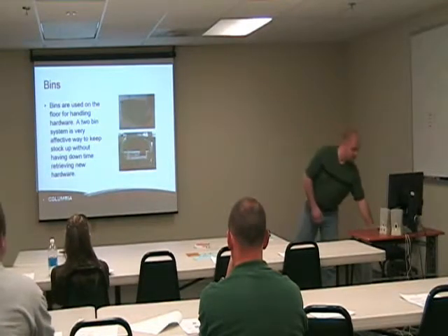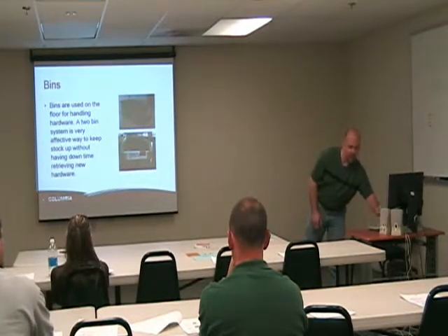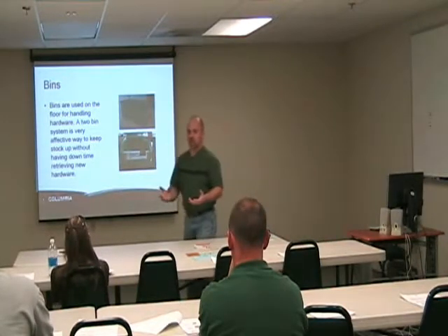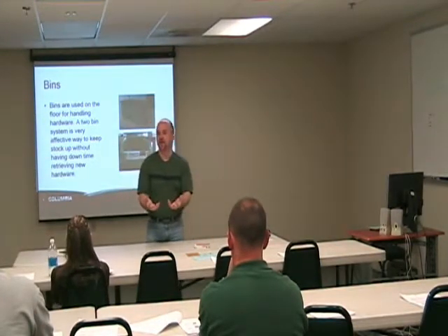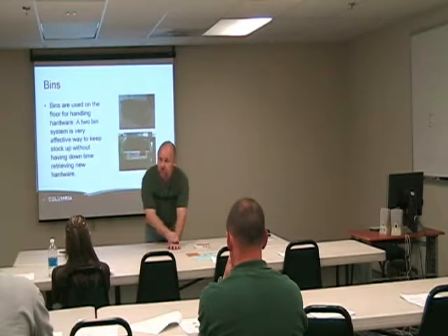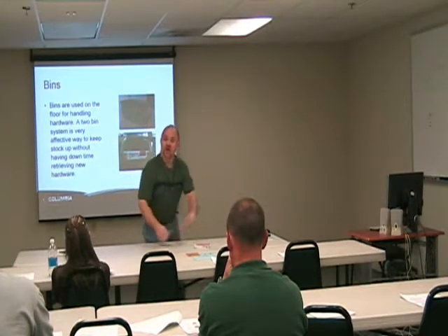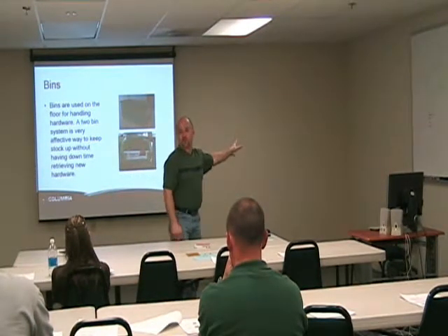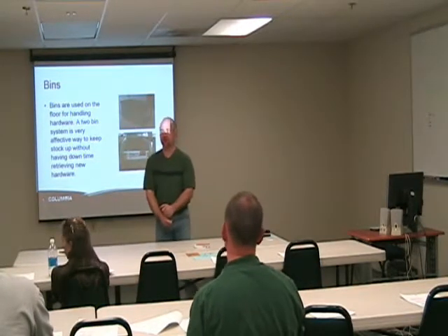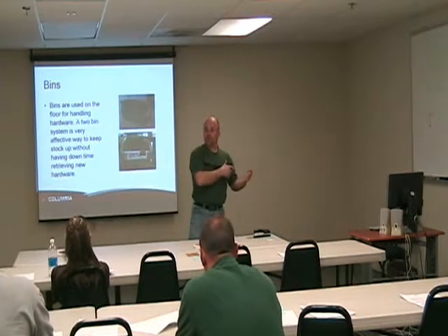Basically, we could have a 2-bin system where you have 2 bins or bags or any 2 type of containers that will hold the same part. So you have the same screw, same part number. When you have the 2 bins, you use up the parts out of your first bin, turn it into inventory. They will refill your part while your guy comes back and works in the second bin. So there's no downtime for them waiting for parts to come back from inventory.